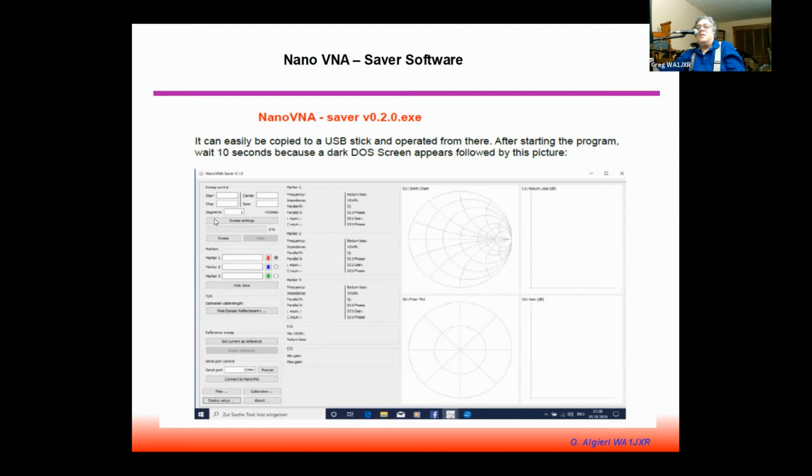The other thing it does here is you see this where it says segments, and you do a sweep. So if you're doing a measurement from some start to stop frequency and you have your segments set at 1, it's going to take those 101 points and distribute them between your start and your stop. But if you set that segments to 10, it's then going to break that start-stop frequency up into 10 segments, and it's going to apply those 101 points to each of the 10 segments. So now you've got 1,000 points between your start and stop. So this is communicating live to the Nano VNA through the USB interface? Yes, it is. Awesome. Yep. And so it takes a little longer. You'll actually see it fill in the graph as you tell it to sweep for these various segments as it's talking to the Nano VNA. But you'll obviously get a lot more resolution in your data plots.